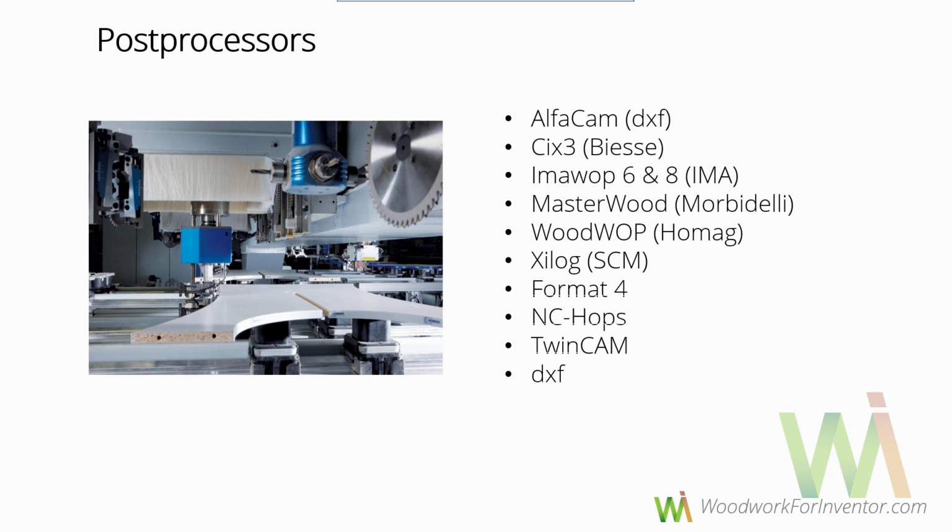configuration. When we have all the possible technological operations, the next step is to explain to the CNC machine what we want from the machine itself: what technological operation should be done. This explanation should be done in different languages depending on the front-end application. And as you can see on the right-hand side, we are working with AlphaCam. We can produce DXFs in a special format for the AlphaCam machines.